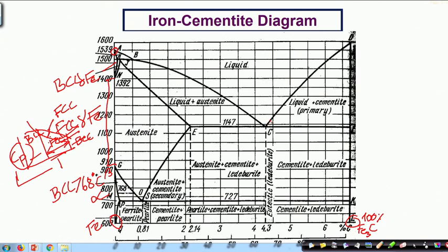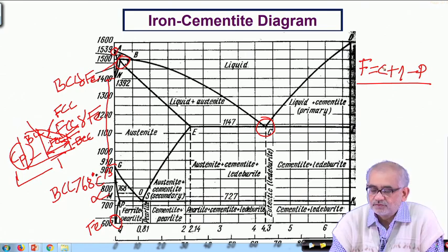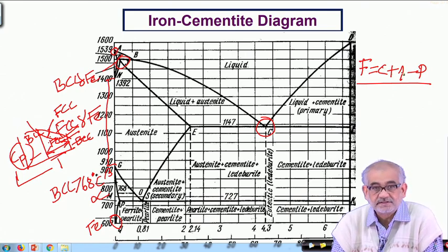We also see that steel will have certain transformations which are called invariant transformations, and these invariant transformations are dictated by the Gibbs phase rule, which says the degree of freedom is equal to the number of components present plus 1, which represents here only the temperature, but actually it can be 2 if it's a non-condensed system where both influences of temperature and pressure are important.